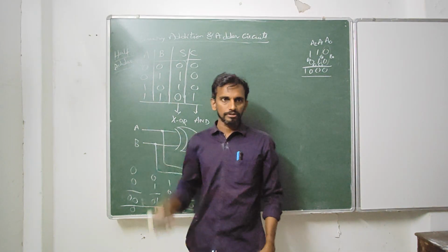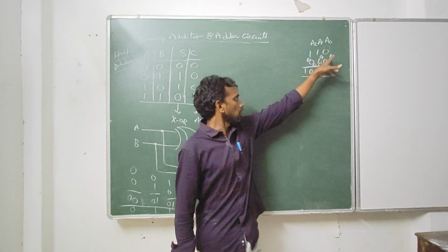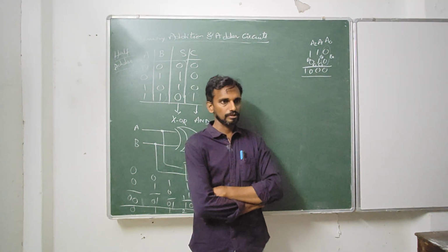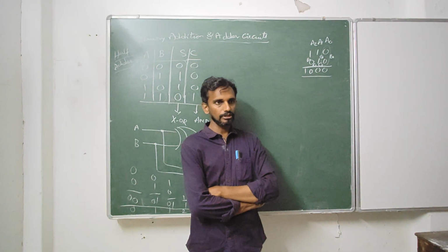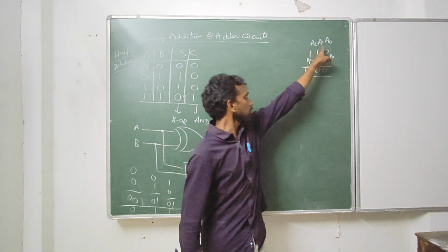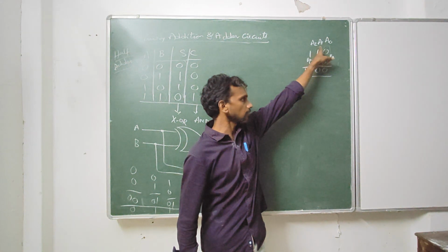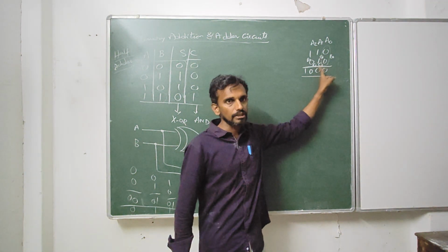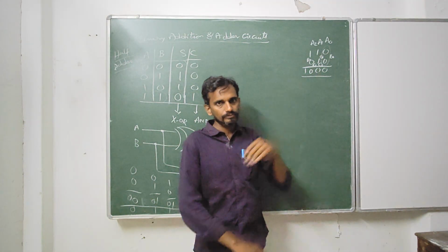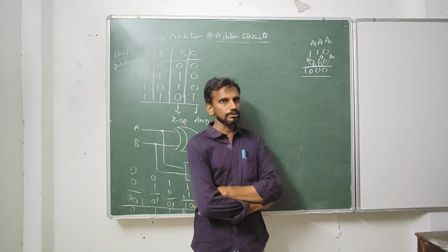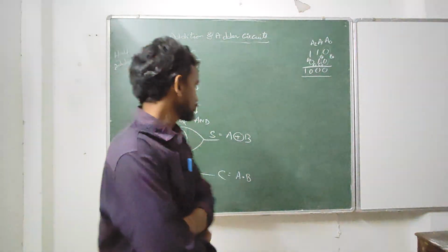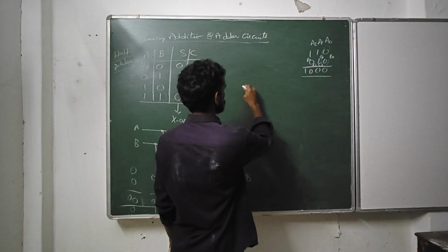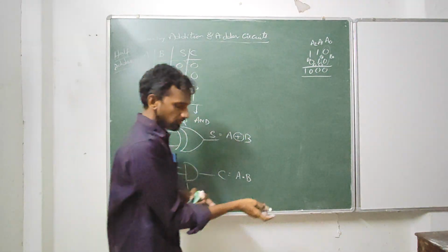So this performs only half of the activity. It adds only 2 numbers. But for the complete operation, we need to add sometimes 3 numbers also. I mean 3 digits need to be added. One is the digit from the first number, the digit from the second number, and carry from the previous state. So all the 3 need to be added. So to develop a circuit, at least first of all the truth table, to add 3 binary numbers.